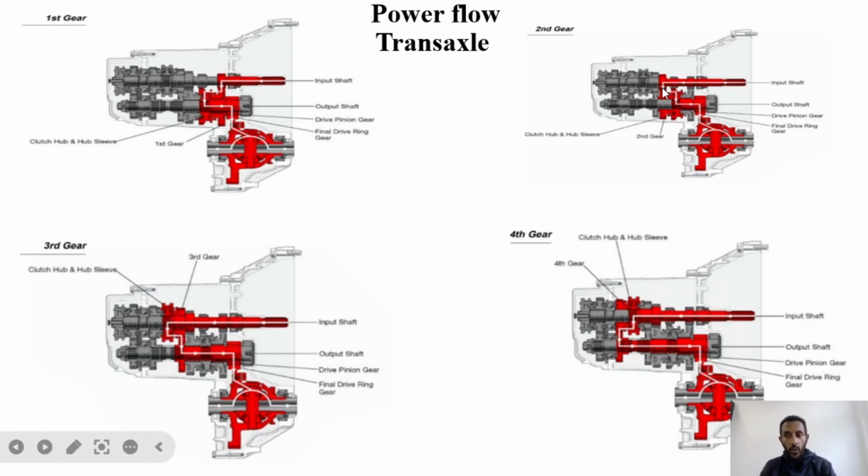Again, in the second part, if you observe, it's the next, which means somewhat bigger than the first. We call this one second gear, and it will transfer to the wheel by means of the differential. The third gear, again, uses the next gear, which is bigger than the second, and transfers. In this part, what you need to know is we cannot create direct drive by connecting shafts directly, because these shafts are not in one line.